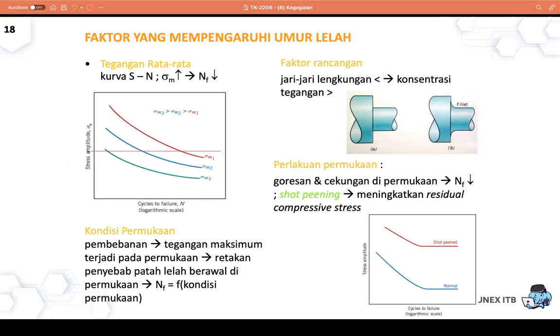Also, to increase the fatigue limit and to reduce fatigue, we can change the design. Rather than a very sharp edge like this, we make a fillet like this, lebih rounded. Then the stress concentration will be distributed.